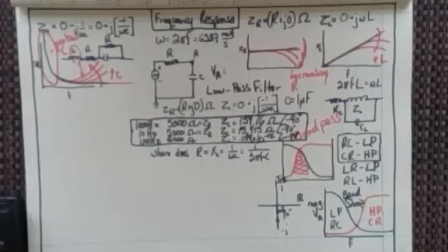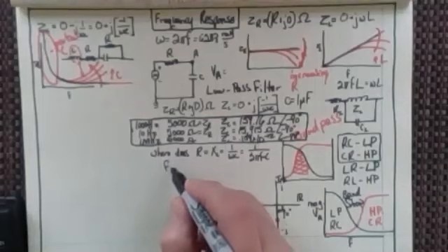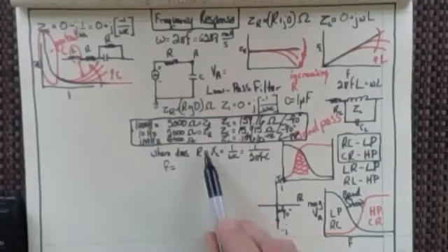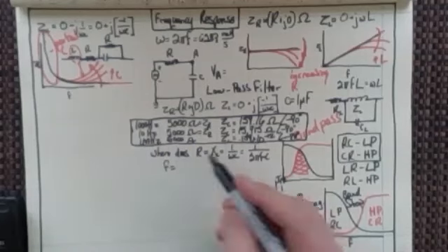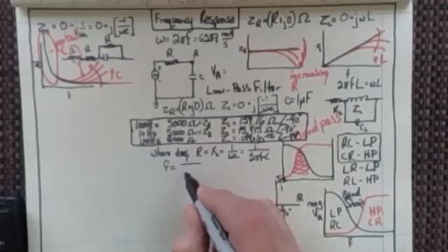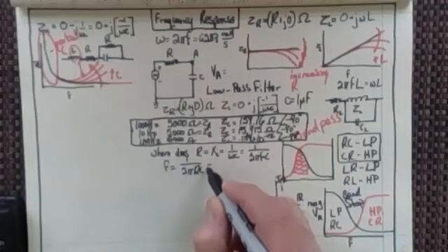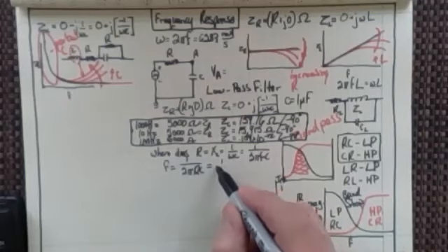So where do these two things equal each other, at what frequency? Well, let's take the frequency out of the denominator on the right-hand side and put it in the numerator over here, and then take R and put that down in the denominator here. So that would just be 1 over 2 pi RC, right? And so let's find that.